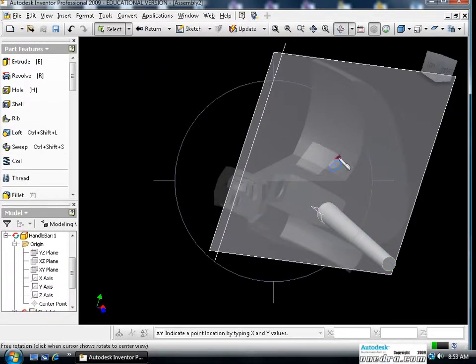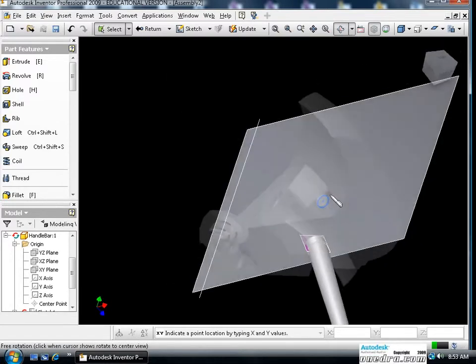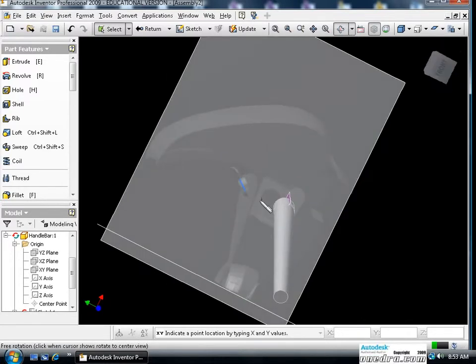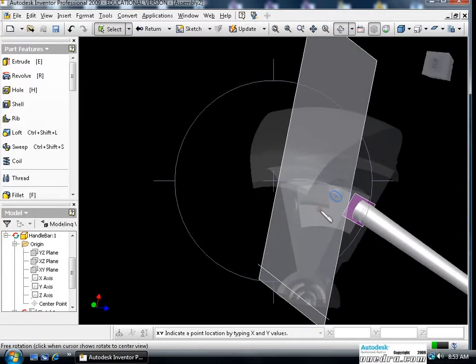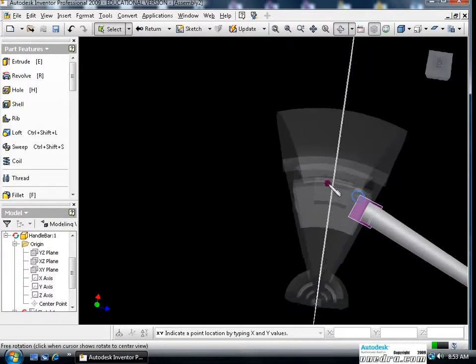So now I've just created this part using the assembly. So when I save the part, it's going to ask me to save the assembly and the part, which is pretty good in Inventor if you're designing the part using the actual model. My next step is I'm just going to build a little T crossing here. Stop about halfway, and I'll mirror to the other side. And I'm going to wrap a bolt on each end to lock the handlebar into place.